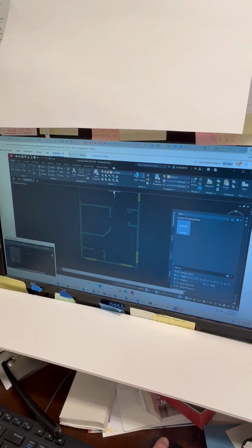Look, oh crap. I just changed this. I forgot I had this guy selected. Let me hit undo. Well, actually, that's a good thing to show you. Look at this. We added these windows in, and we had the A glazing layer on, and you'll notice, as I mentioned, how layer 0 has the special capability of, if you create the geometry of a block on layer 0, when that block is inserted, it will inherit the current layer.